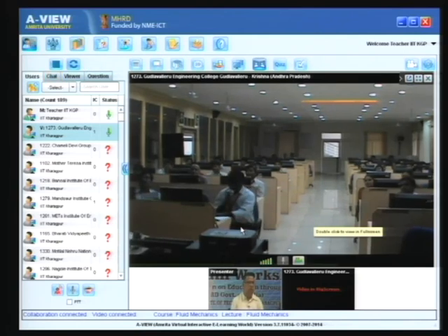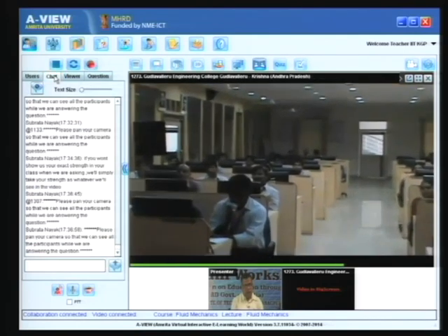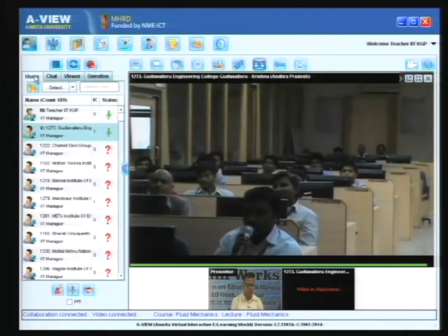Hello, good evening, sir. Good evening. Sir, I want to know, will there be any difference between thermodynamic pressure and hydrostatic pressure? Okay, if it's a compressible fluid which is flowing, there is a difference. If you have an incompressible flow, then the two will be the same, even if the fluid is deforming. For compressible flow, if you accept that the Stokes hypothesis is valid, then the two will be the same. So when you study viscous flows, the Stokes hypothesis may be covered.